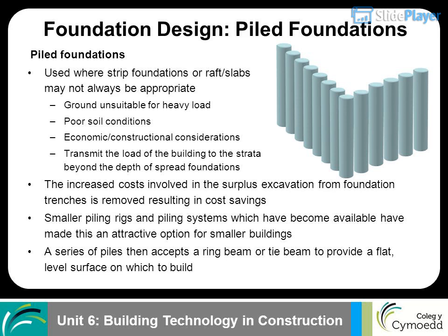Foundation design: piled foundations. Used where strip foundations or raft slabs may not always be appropriate. Ground unsuitable for heavy load. Poor soil conditions. Economic and constructional considerations. Transmit the load of the building to the strata beyond the depth of spread foundations.